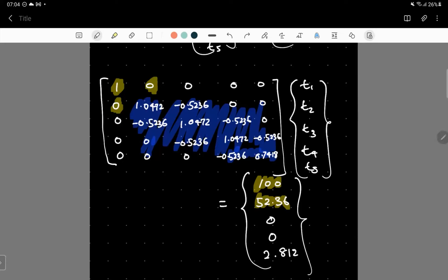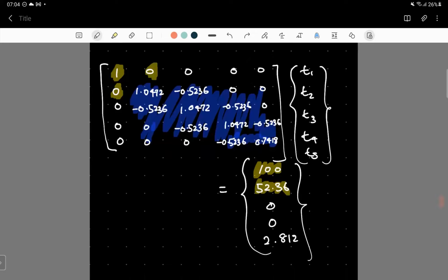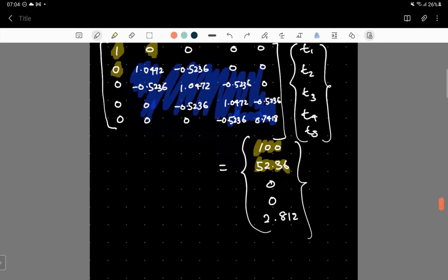And the first row of the matrix has been set equal to the known nodal temperature at node 1. You can see 100 Fahrenheit degrees has been set on the right hand side as the first element of this column matrix. So, of course, the second element in the force matrix has also been replaced. If you look closely, it is being replaced using this equation.